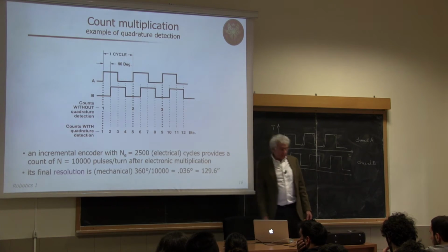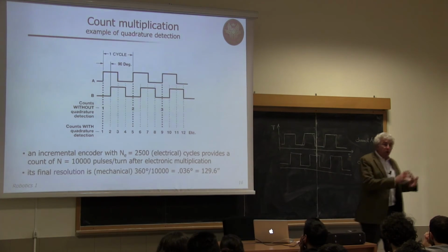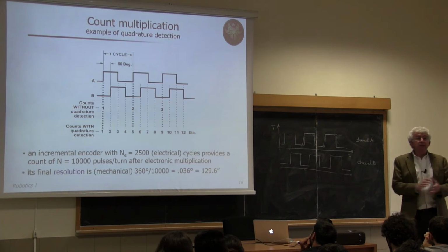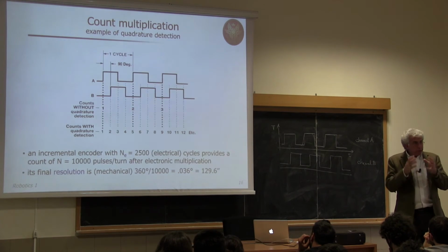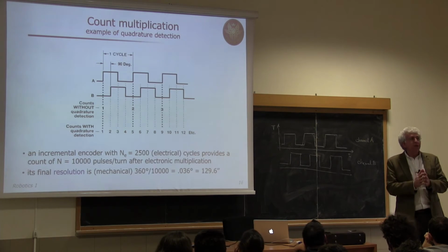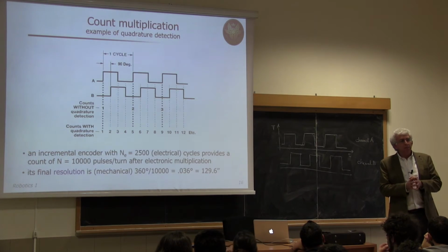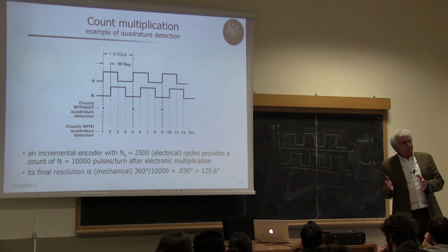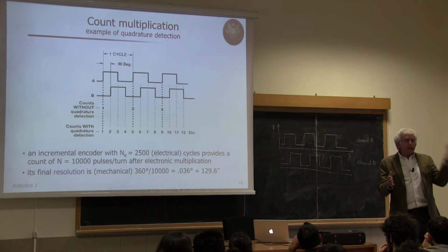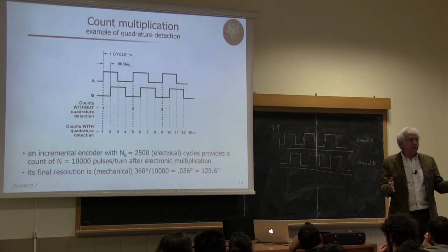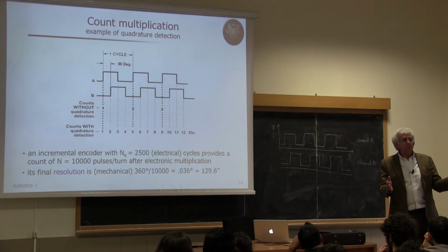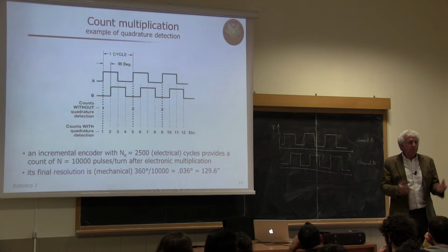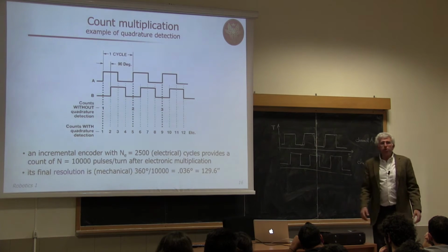We have seen, for instance, in the DLR exploded joint view, you remember that picture, that because they were using a harmonic drive, which is known to be an elastic transmission, they had some electronic sensing of position on the motor side and another sensor, actually a Hall effect sensor, measuring position beyond the transmission. Okay? Just to make sure that all information is there.